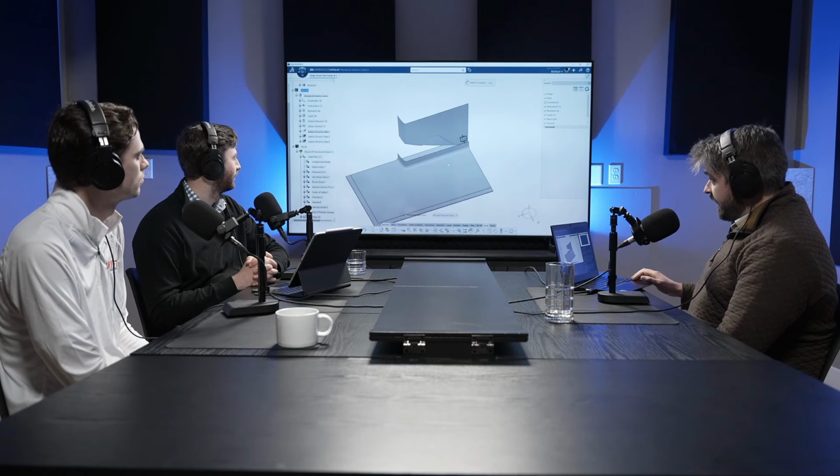Fully defined. Good job. Shrink it right down. So we bring it right back in, and then we can run that simulation again. With a smaller part, we can see a lot less stress. So you just had to click refresh. You didn't have to go through and apply the clamps, the forces, or anything. Yep. It just pulled the updated geometry in and had all of the setup remain.